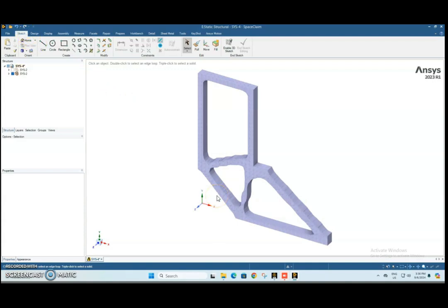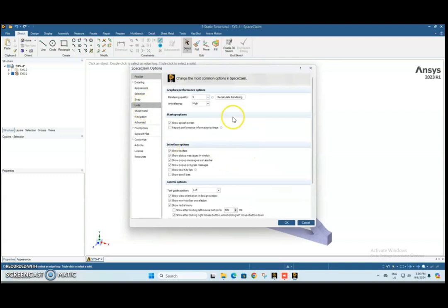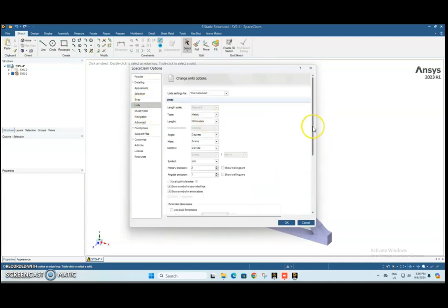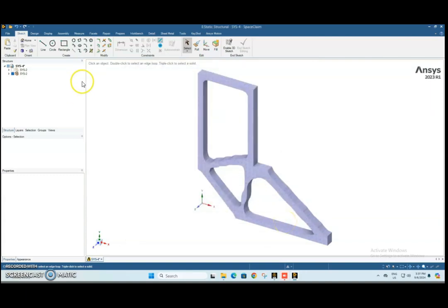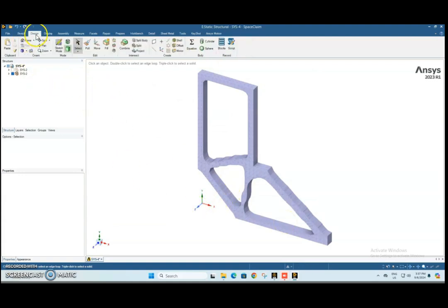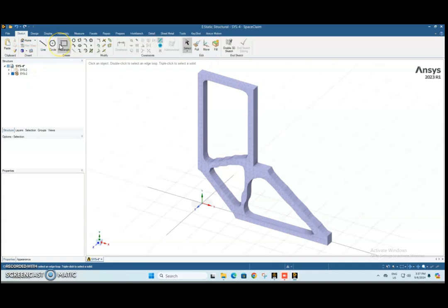So now we want to build a 3D model based on what's being topology optimized, right? Before we start, we probably have to check back under the units to make sure we are in the same scale, millimeter. Here we have to put 5 mm so that we have the same scale. Then what we can do now is go to design, sketch mode.